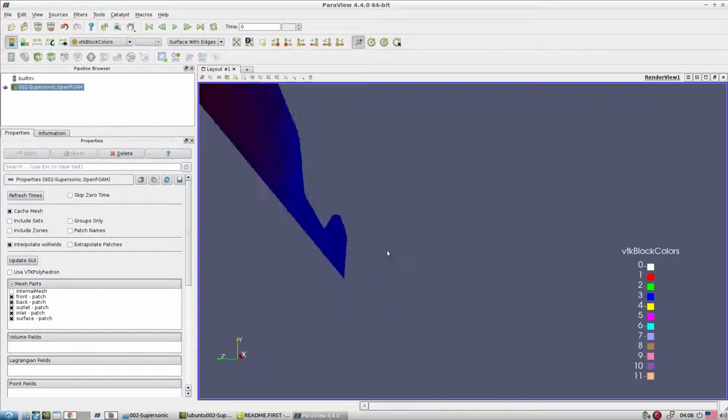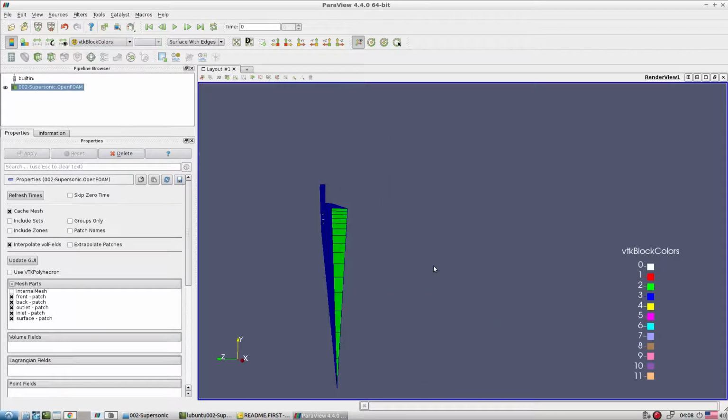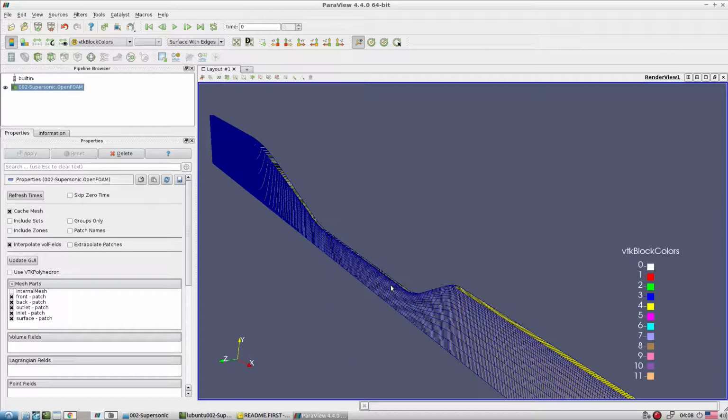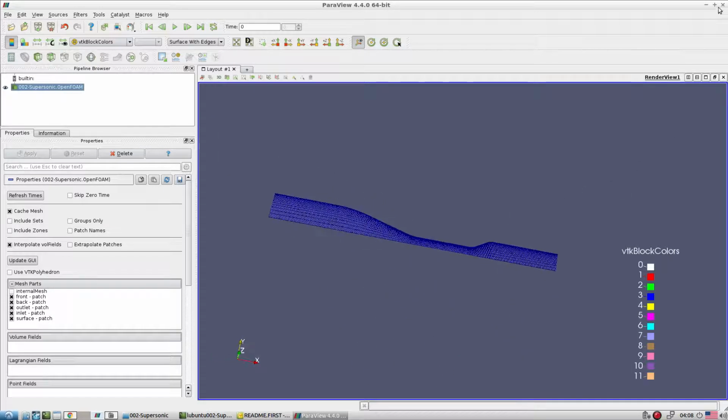So I hope you understand. On this we specify, so we are simulating a very small sector of the entire circular cross section. For that we have a very nice condition in OpenFOAM, that is the wedge condition. So that is what we specified here.